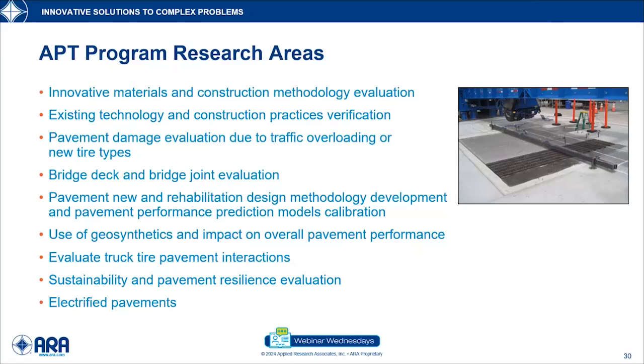Well, the only way for the agency to test this is to actually use these materials, build a test experiment, and do a long-term pavement evaluation of the material. By the time that test site has been tested and the material has been used in real in situ conditions and real traffic, probably ten years have gone by, and that technology is not new anymore. There's something even better, something new that comes into play. So there is a significant challenge for an agency to test new materials, and this goes along with new construction practices as well.